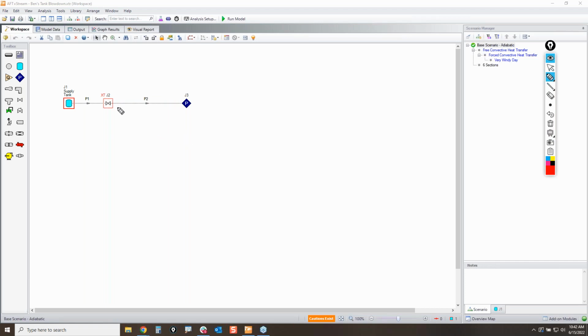So in reality, you're going to have a situation where you have air in your system, and as this valve opens, the nitrogen is going to have to start pushing the air out of the system before you start to see nitrogen exiting. That's not what the model is going to show. It's going to show densities in this pipe based upon nitrogen, where in reality, they're going to be air densities initially until the air is evacuated. So that's a very important assumption I just wanted to make clear that we're dealing with right here.